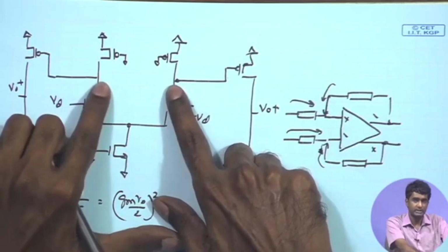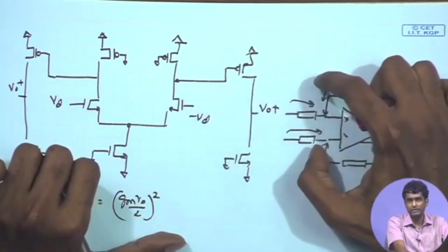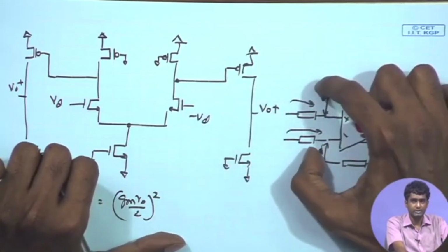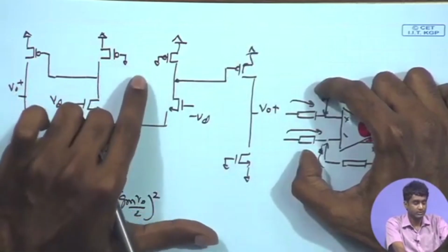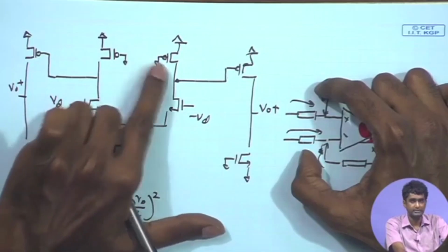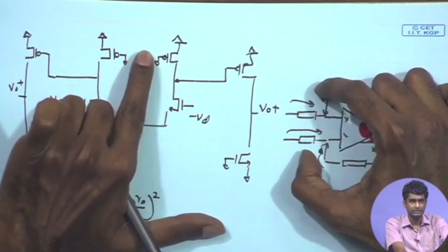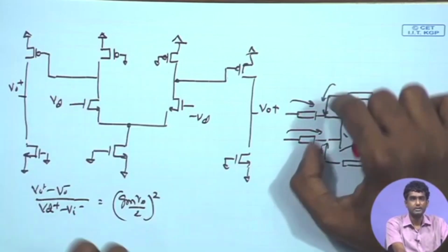So the common mode signal anyway will be small, but apart from that, the bandwidth of the error amplifier can be made potentially very small so that it does not propagate any significant component of the common mode signal. As a result, you will just have a DC bias point. So that is the reason why we have put an AC ground over here, assuming that this is a relatively constant DC potential provided by the common mode feedback circuit.